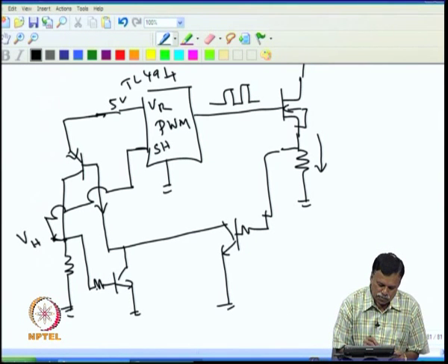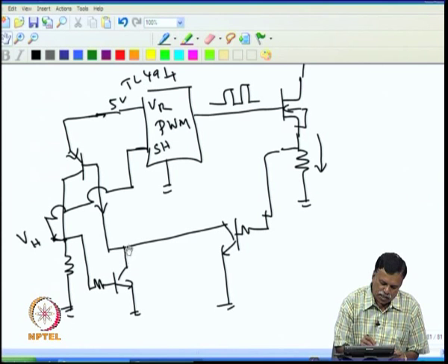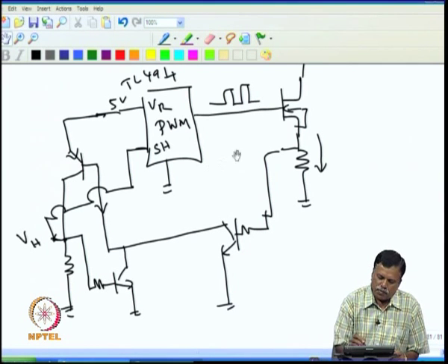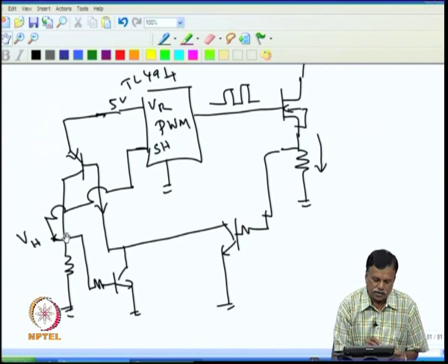Now to make this transistor go off again, because once current goes off, this transistor will be going off, but nevertheless this will not go off, because this already triggered and it caught the voltage here, and this will continue to be conducting, and this will continue to be high. So the pulse had disappeared, current had disappeared, but the triggering voltage, that is the voltage which switched off the controller, still will be there. So when the next pulse comes, we have to reset this, then only the next pulse will appear. Now this is normally done using